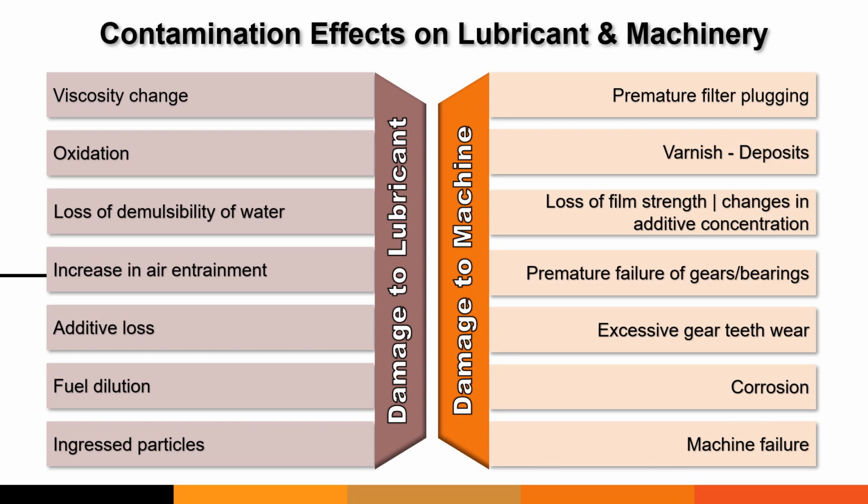Mixing two incompatible lubricants of the same viscosity can still cause the anti-wear or extreme pressure additives to be reduced to flock. If we increase oxidation rates, the sludge and varnish byproduct buildup will reduce the ability to transfer heat. A final warning. The most common cause of cross-contamination is the inadvertent application of opposing fluids.